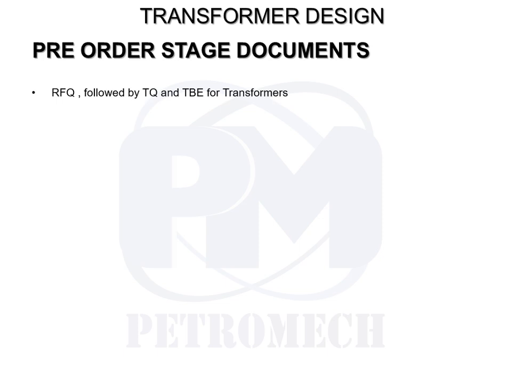Once all the technical queries are done, we furnish a technical bid evaluation sheet. If there are 3 vendors and we have multiple parameters mentioned in the data sheet, we prepare a technical evaluation sheet wherein the data of all 3 vendors are put forward to view the compliance, non-compliance or deviation with respect to our required data, whether vendors are meeting those particular values or not.